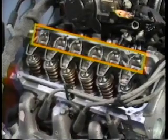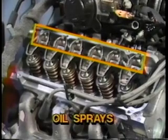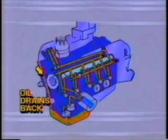From the push rod, the oil sprays out over the rocker arm and other valve train components. This spray coats the upper engine components with oil to provide the necessary lubrication. Now, what I want you to note here is that lifters were pressure lubricated, but the upper engine components, meaning the rocker arms and valve springs, are lubricated by the oil that then drains back from the cylinder head pan. That's how the basic lubrication system works.